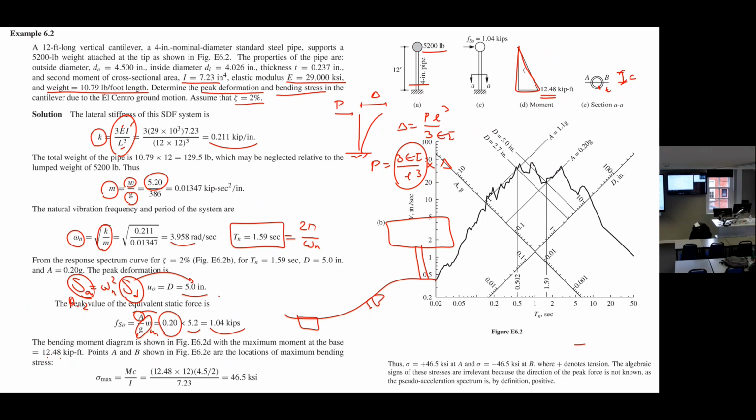You have some upper grades, something like 340 and 400, but usually you use ordinary conventional steel, which is 235. You could use high strength steel to satisfy this kind of stress, but assume we don't want to pay too much, so we are using ordinary conventional steel, and the yielding stress is 235. Obviously, this stress is more than that, and this is not acceptable.